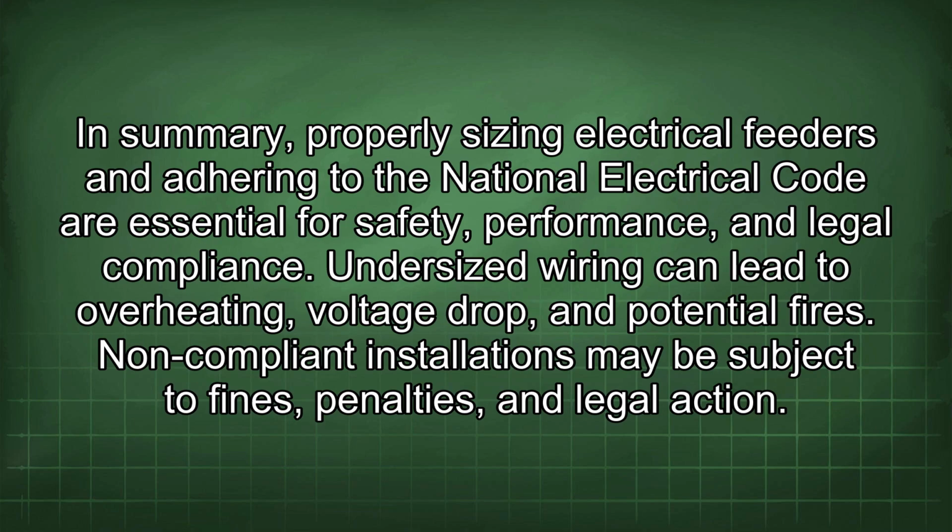In summary, properly sizing electrical feeders and adhering to the National Electrical Code are essential for safety, performance, and legal compliance. Undersized wiring can lead to overheating, voltage drop, and potential fires. Non-compliant installations may be subject to fines, penalties, and legal action.